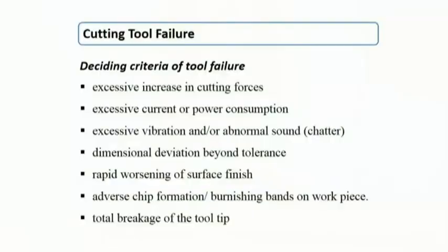Another indication is that if the power consumption is suddenly increasing, then also you can get an idea that the tool has failed. Because if the cutting forces increase, that means your power consumption will also increase. Then the cutting forces are larger because of the failure of the cutting tool.